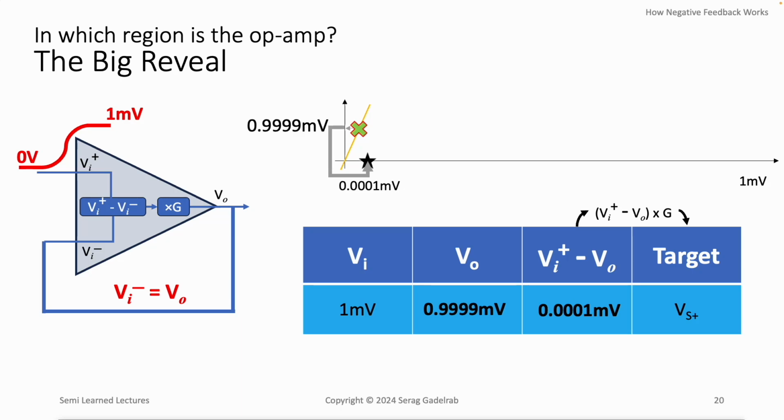The target voltage will therefore also drop from the supply voltage to just 10 millivolts. This new target will keep the output voltage moving higher, but towards a much smaller target. Let's assume that it moves up by a minute amount to just 0.99999 millivolts. That's 5 nines. The difference has now become even smaller. It's become 0.00001 millivolts. And that gives us a new target of 1 millivolt.